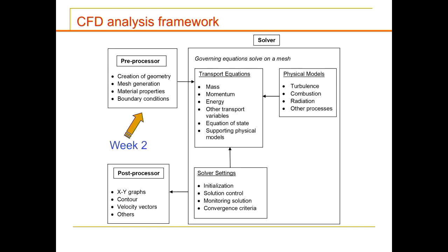So the inertia and the viscous effect is actually linked to the advection term and the diffusion term. That means that for laminar flow, your diffusion term dominates over the advection term, and vice versa for turbulence. So what drives the flow at the end of the day is your source term. If you've got a high pressure gradient, that will drive the flow more, and you get more inertia, and you have a certain characteristic of turbulent flow.